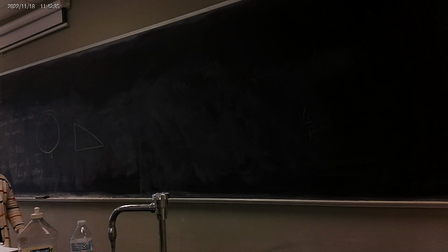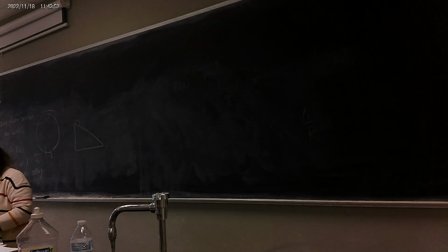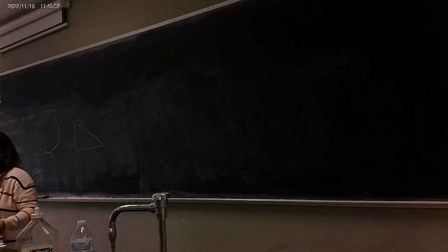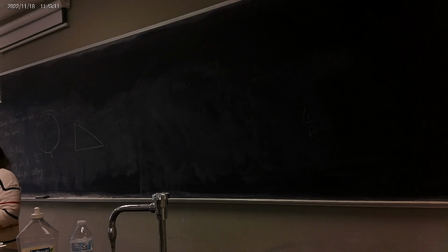It has to maintain contact with the road all the time so that it does have a static friction between the tires and the road. As soon as it is sliding in any direction, it's going to have other friction, which is less than the actual friction. There will be friction, but it's less. It's sliding, it's not rolling. So there is a misconception about rolling friction, that it is a kinetic friction because it's moving, but rolling friction is not a kinetic friction. It is a static friction, because every point during rolling is in contact with the other surface at some point.